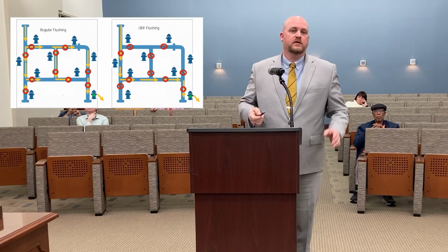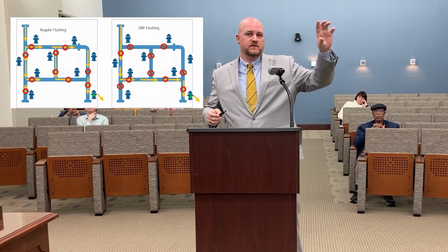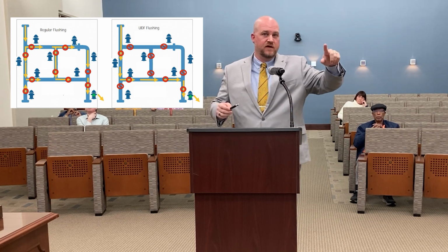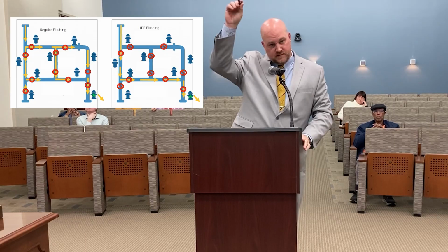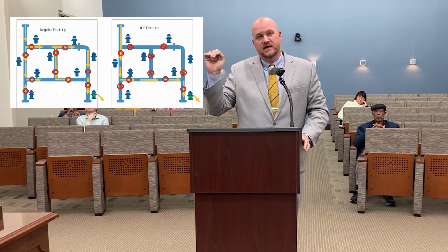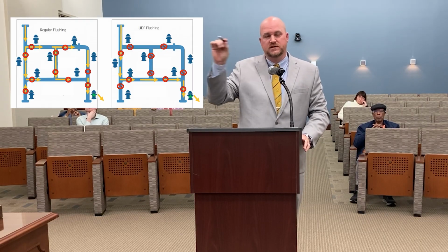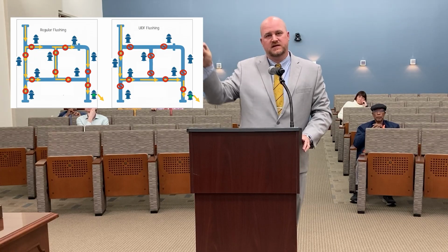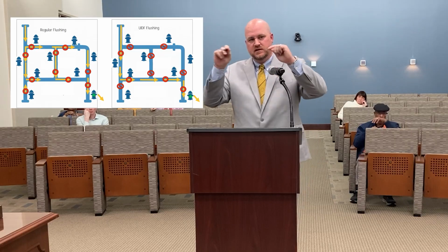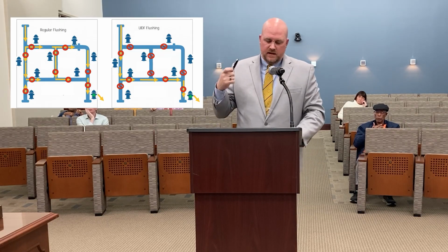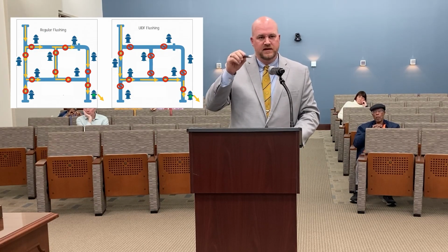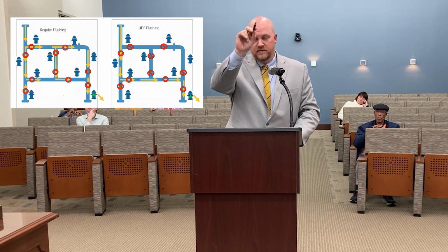and I'm sorry I don't have a pointer, but you have a hydrant on the far left-hand side here that has a circle. You would close that valve, and then you would go to the next vertical road, you would close that valve. And then you would go to the next vertical road and you would close that valve. And what it does is essentially it forces water to go through certain ways, so you're cleaning the top pipe. Then you would go through and you would open your valves and do the same thing with the bottom pipe. And it's strategically done. And with that, you're looking at it as a pilot program, but what it's basically doing is you're developing a standard operating procedure to go clean this specific line.